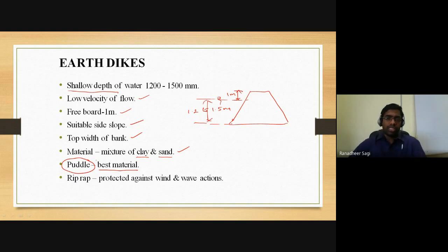Wherever you find openings that are going to cause seepage across the cross section of that earthen dike, you are going to arrest the movement of water flowing through by applying the puddle material over the surface. And you'll also be using what is called a riprap material. Riprap is nothing but your large aggregate particles, which are placed on the sloping surface of the embankment, to prevent failure of your embankment slopes, and also to ensure that wave forces because of the water movement do not cause failure of the slopes of that embankment.